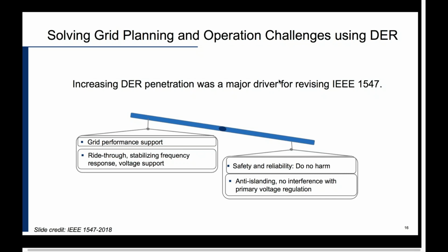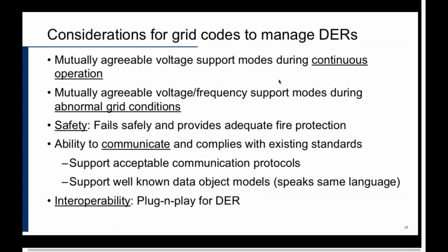In the past, all these systems used to just generate active power and shut down when there was any problem, whereas what's expected from now on is to also do something when there is a little bit of a problem on the grid, could be voltage, could be frequency, or anything. Additionally, as the penetration of these DERs increases, instead of investing in additional technologies to mitigate issues, utilities can use these systems to provide some service.